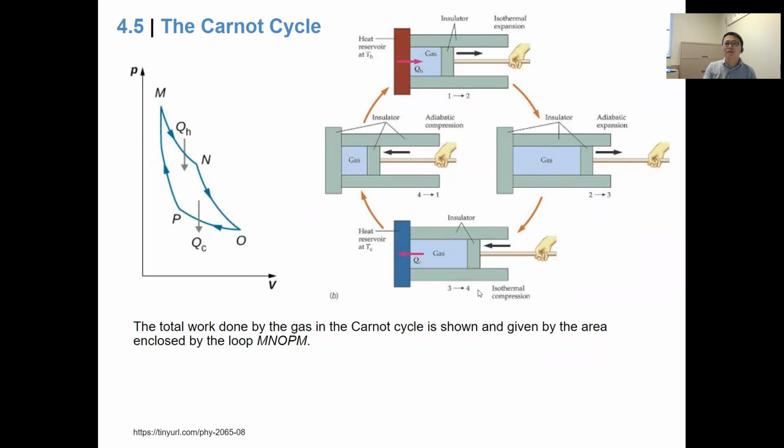If you start from a particular point, whichever it is, the total work done will be the work enclosed by the cyclic path. Heat in and heat out you can also calculate from the PV curve, so at the end you can calculate the efficiency of this engine.